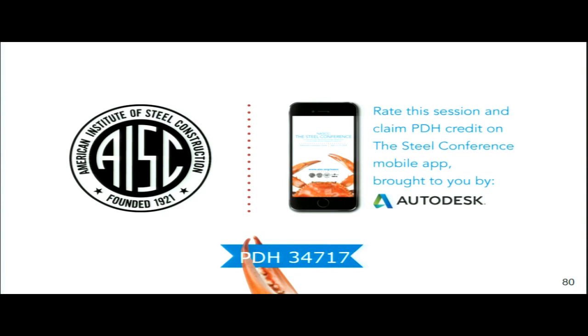What about Anthony? One of our colleagues, Anthony Barrett, did a thesis or dissertation on finite element modeling for our types of purposes, and in his case, he had brick walls, and so he had vertical slip connections at the exterior studs, and these studs still behaved like partially effective load-bearing walls. We account for that in our models based on his recommendations of increasing the moment of inertia by 2.5. He just calibrated that based on the test results. And we use that for all of our models at spandrels that have any kind of decent cladding there at all. If the cladding totally bypasses the floor somehow, but it's probably not going to, then you would not, obviously. But that's probably the closest thing as far as I know to this research, but somebody may know that somewhere in the literature.